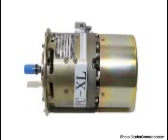The two stationary brushes are placed on opposite sides of the commutator and are so mounted that each brush contacts each segment of the commutator as the latter revolves simultaneously with the loop. The rotating parts of a DC generator, coil and commutator, are called an armature. The generation of an EMF by the loop rotating in the magnetic field is the same for both AC and DC generators, but the action of the commutator produces a DC voltage.